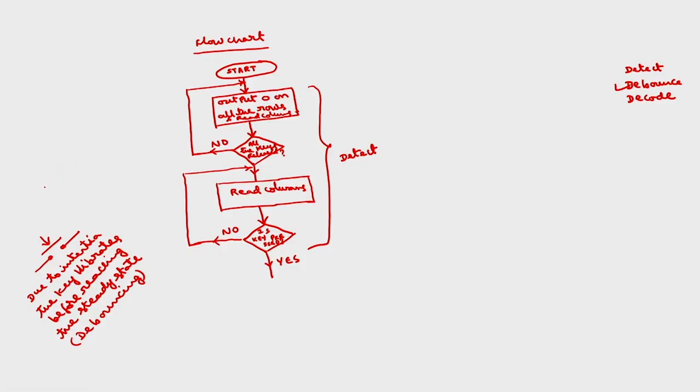That is, if I make a low to high transition, instead of going to high, it vibrates. After some time it will settle at high. This is logic 0, logic 1. This is due to bouncing. The reason for bouncing, as I have told, is inertia. Because of the inertia in keys, there will be bouncing.